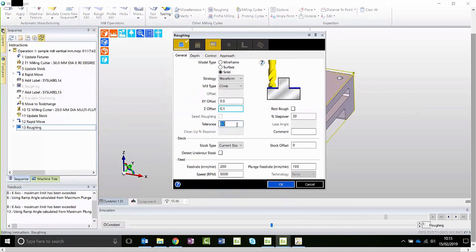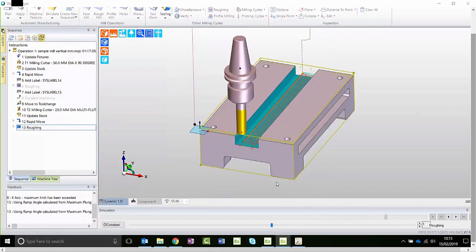So let's do it again. In this one here, command dot, and this time I'm going to use Z offset. Double click on the Z offset, maybe divide that by 2, click out of the box. Now all these 3 fields are linked. If I change the first one, you'll see the others change accordingly and relative to this first one. So let's take that back to 0.5, let it calculate. It's another little time saving, whereby we can keep everything relative to other options within the cycle.